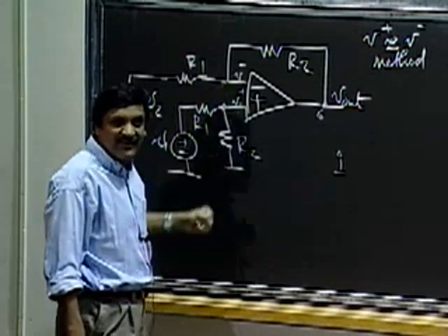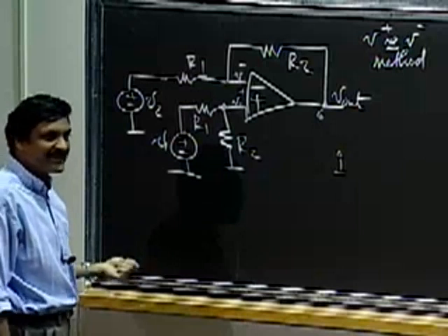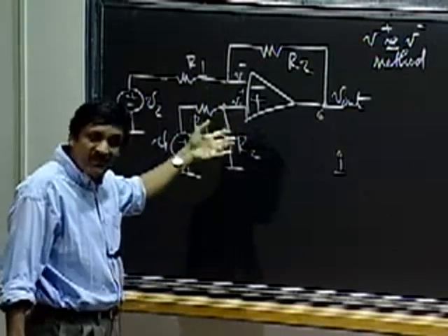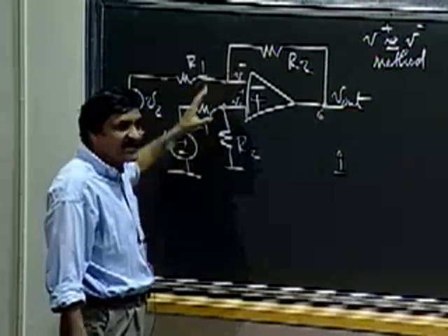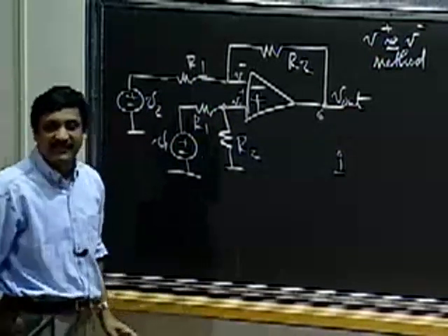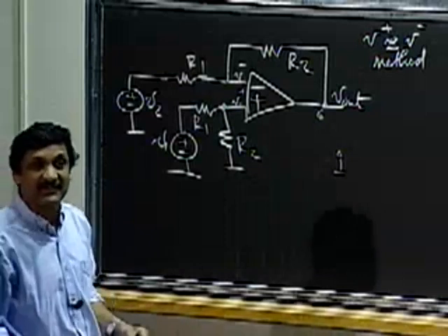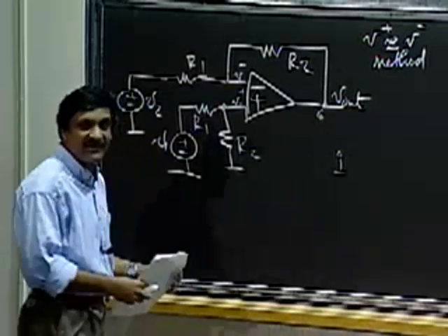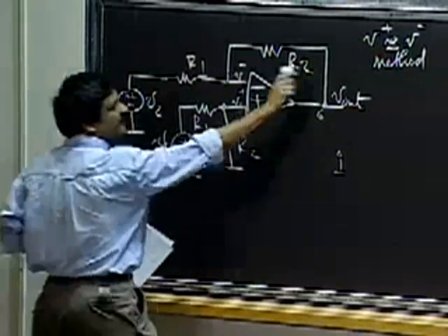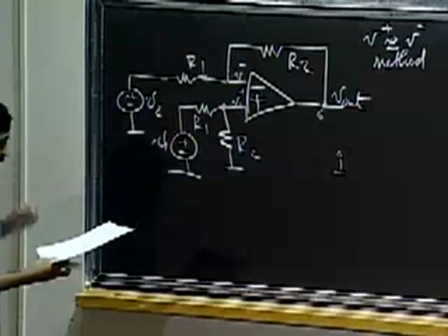This is just a bit of inverted logic. The circuit is going to make that happen, so to analyze the circuit in its steady state, why don't I just go ahead and assume that to begin with? This again goes back to us wanting to be engineers here and do whatever's simple, and find the simplest possible way of getting someplace. So I'm going to use the V plus equals V minus method.